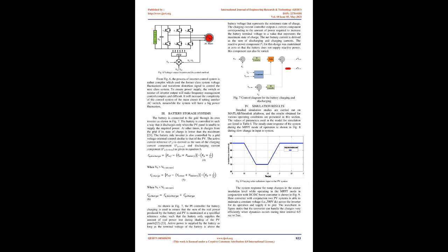The control system mainly controls the maximum power point tracking of the photovoltaic array, and the current waveform and power of the output of the grid-connected inverter, which makes the output to the grid correspond with the power exported by the PV array.